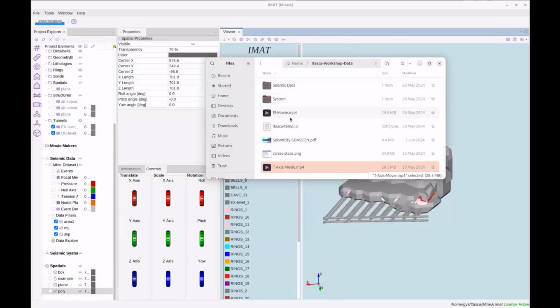There's also another source parameter called seismic energy index that's extremely useful. Seismic energy index is the seismologist's parameter to determine which areas of the rock mass are stressed and destressed. Areas of high seismic energy index we consider to be higher stress. The event occurs in an area that's highly stressed, and with low energy, it means the event probably occurs in a region of softer rock or already fractured rock, for example, closer to a cave.